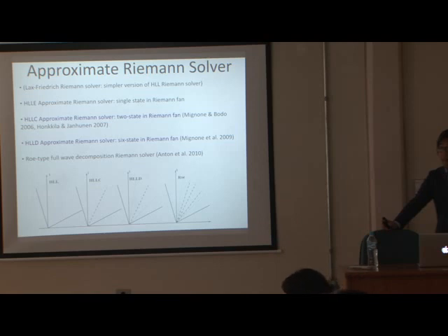Since Roe is the most precise Riemann solver solution, you have some numerical fluctuations that could produce negative values. But the fact that we take everything into account means the system can select the best characteristics in this sense, so it might decrease the noise, because of the precision.